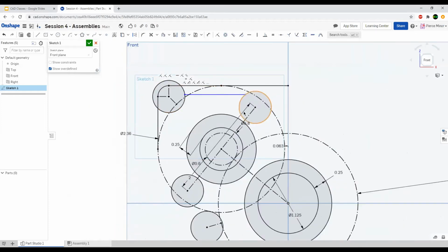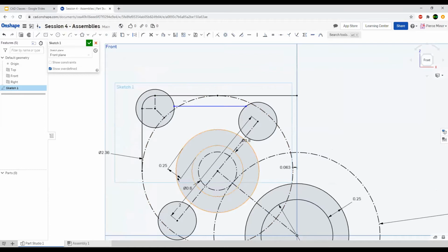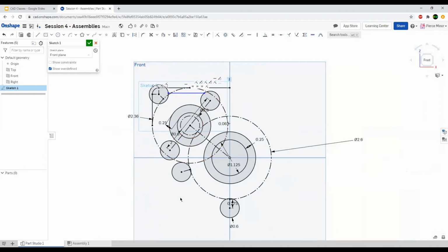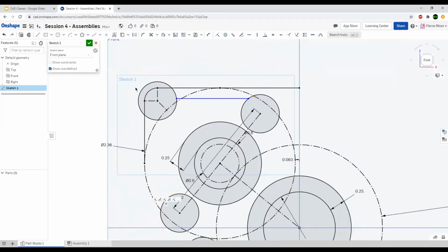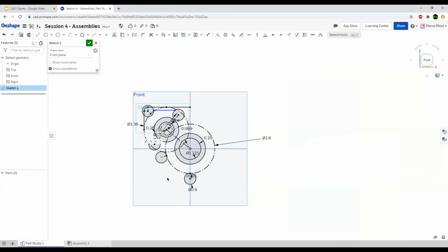So anyway, we're currently trying to create a frame for the gearbox. We have all the circles we're going to need. We just need to actually connect them together. Let's start with the external frame. We want to have a 1/4 inch border that goes around the entire thing. And here we're going to want it to be curved. Actually, we'll probably ignore that circle because it's not completely necessary to go out to there, and then there. And then we'll go down to there. I hope that makes sense.